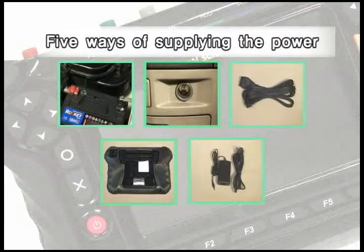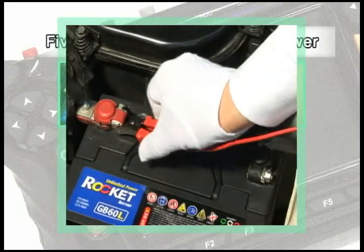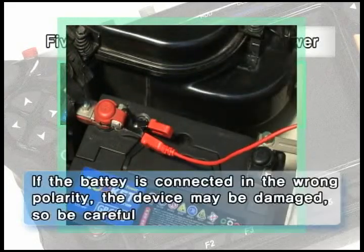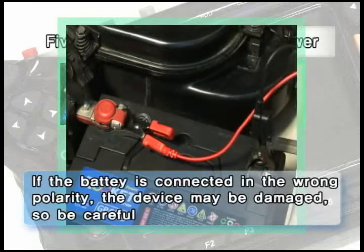We will go over in detail the 5 ways of supplying power. First, if using a car battery, connect the battery cable to the battery in the correct polarity. If the battery is connected in the wrong polarity, the device may be damaged, so be careful.